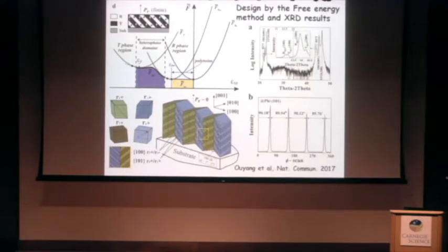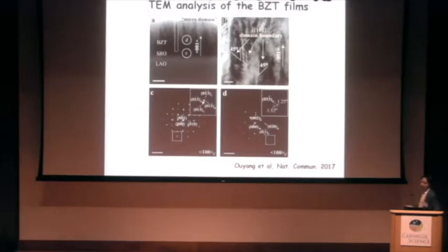And you can see actually there are 2 peaks on the BZT. One is tetragonal, one is rhombohedral. And we did phi scans of both peaks, showing you nice 4 peaks, indicating the epitaxy quality of the film. And we did some very intensive TEM work. We checked 4 different thicknesses: 350, 700, 1.4 micrometer. The thickest is 1.8. Here I'm showing you just one as an example.